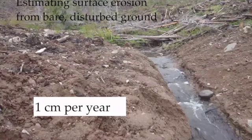Besides road surfaces, for any other surface from which you remove vegetation and leave bare soil, we come up with a figure that the bare soil will generate 1 centimeter of sediment per year. As soon as the surface starts eroding, it begins the process of hardening up. Basically, this means leaving the soils open to erosion and allowing the fines to be eroded away, leaving behind coarser materials less prone to creating mud.